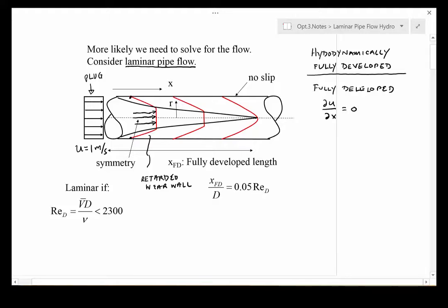Now, just to give some sense of why and how this occurs, it's worthwhile thinking a little bit about our point about the diffusion processes and diffusion scales. So imagine that we're following a chunk of fluid. This is not Eulerian; now we're looking at this in a Lagrangian sense. So we put a chunk of fluid, it's more complicated than that, into the system, and as it goes downstream, we look at the velocity.